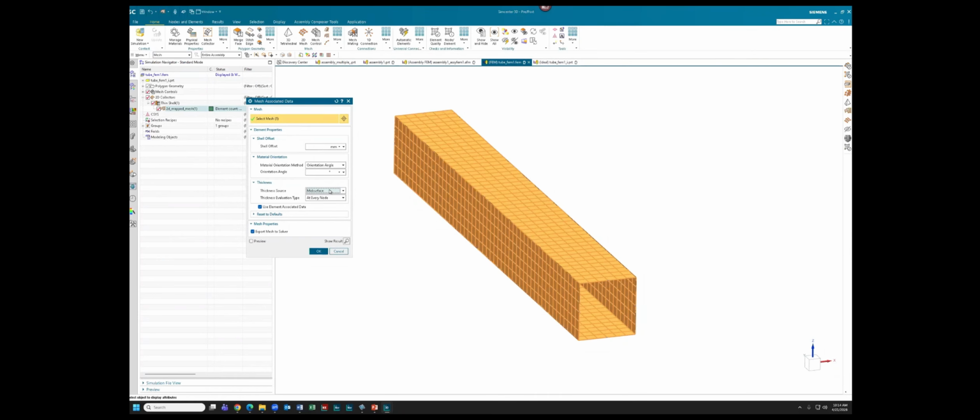You can potentially imagine if you have complicated tapered thicknesses or things like that, instead of having to manually create a bunch of physical properties for those different thicknesses, you can just use this option here. And there's a few different options of how it will evaluate those thicknesses. For our example, since we just have our nominal thickness for this tube, it's going to give us the same result no matter what we select. But again, these can be relevant if you have tapered thicknesses, things like that.